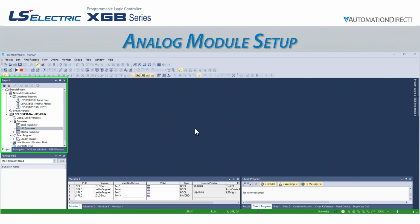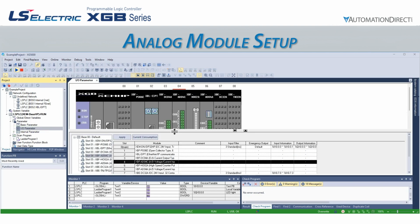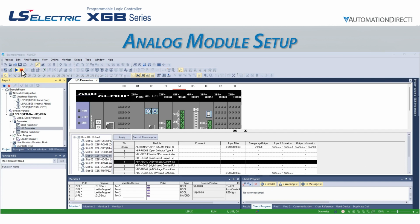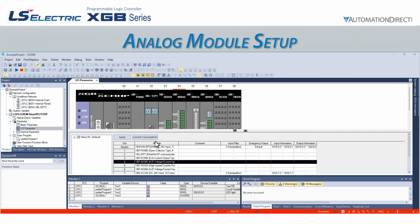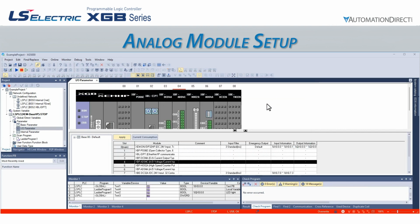To do this, we go to the project window on the left side and double-click on I/O parameter. This opens the I/O parameter screen. We have already added the expansion modules attached to this PLC in a previous video. For a brief recap, we can add modules automatically by putting the CPU in stop mode, going to Online, System Diagnostics, I/O Information, and clicking the I/O Sync button. We can then click the Apply button, and the software will create any required variables for our I/O.